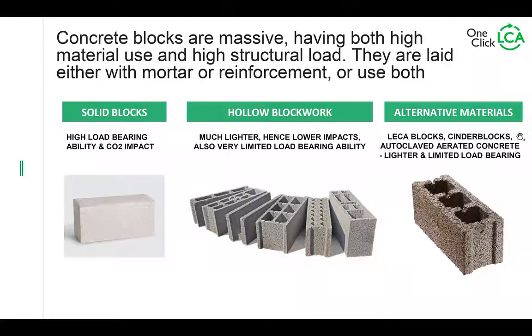And on the other hand, we do have some alternative materials which provide some of the benefits as well. So leca blocks, so light expanded clay aggregate, cinder blocks, which are basically ash mixed with concrete, autoclaved aerated concrete, and all of these are lighter and do have some limitations on the load-bearing ability. However, because these are all also lighter materials, they do not have to have the exact same load-bearing ability as your classical solid block-based wall would have to. So these are the main considerations in matter of blocks.